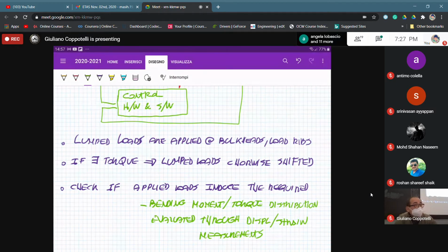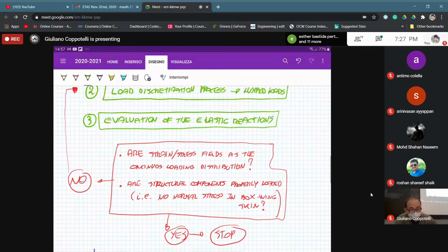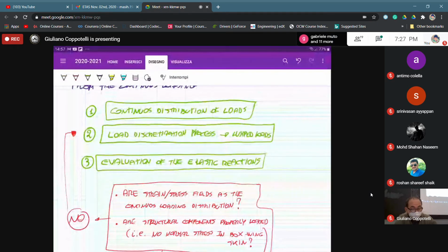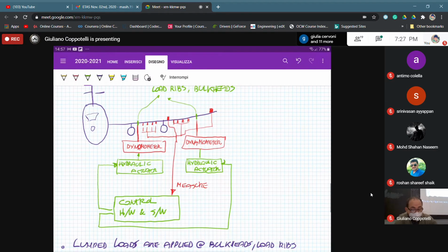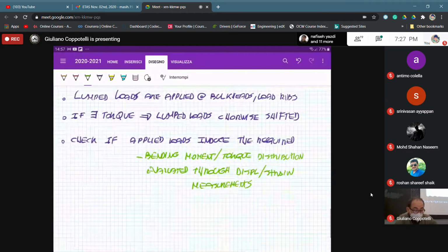Once we are here, there is not too much time to spend in doing that, because we already have sort of iterative procedure that has been already considered. Okay, but however, once we are doing this, we are exciting the structure where it was supposed to be and just check that everything is fine, and then we take the measurements, and then we static test the structure considering the limit loads, ultimate and final failure.